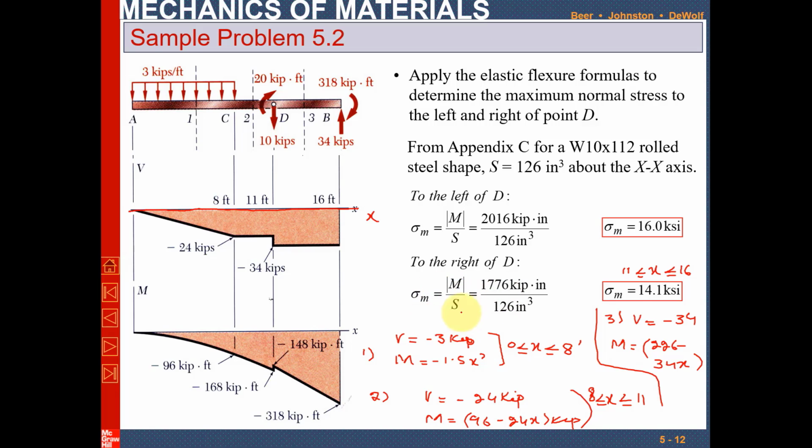So first we will draw the shear force. We will start from x greater than or equal to 0 and less than or equal to 8 feet. At point A you can see there is no concentrated load, so definitely at this point the shear force will be 0. Now by using this equation, this is actually minus 3x.